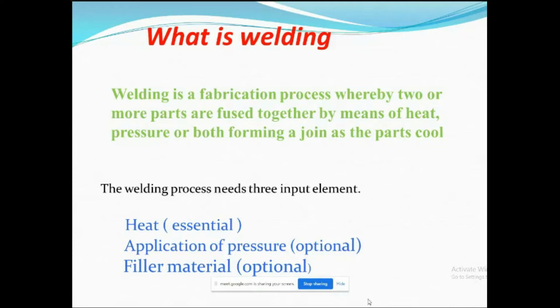With the help of electric resistance, if you look at the fuel tank, these fuel tanks are generally made with the help of resistance welding. In that case there are two wheels. These two wheels are rotated in the opposite direction. We have to provide some electric current on that to heat the two wheels. Whenever we have to start the welding of the fuel tank, we put the fuel tank between these two rotating wheels, and due to the heat, the two parts of the fuel tank stick to each other, and whatever joint we make is a leak proof joint.